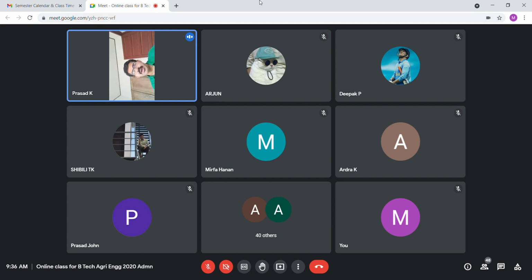Okay, and next is a pitch surface. What is meant by a pitch surface? Pitch surface means it is the surface of a rolling disc which the meshing gears have replaced at the pitch circle. Okay, meshing gears means what? One gear is here and the other gear is here. Then these two gears are meshing gears, that means in contact with each other. While a gear is rotating, the meshing gear is also rotating. That is very important. Then only the power can be transmitted. Okay.